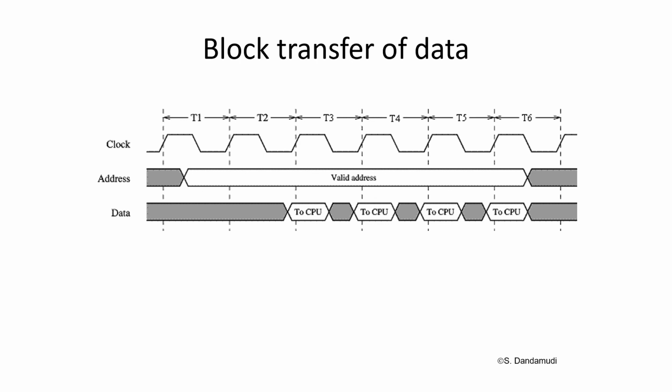A block transfer might request the memory at one time period and then have a wait state where nothing's really happening, maybe multiple wait states. And then at some other point, it'll finally start to transfer the data to the CPU in multiple transfers. In other words, there's the first data block, the second data block, the third, the fourth data block shown here.